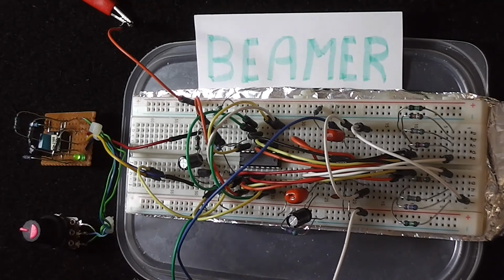One is that it linearizes the variable control, and when I say linearize, it's an approximate linearization. I didn't really want a strange, unusual, logarithmic-ish shape, and I wanted to try and generate as much as possible a linear dial, and that I managed to achieve relatively easily with a single transistor.